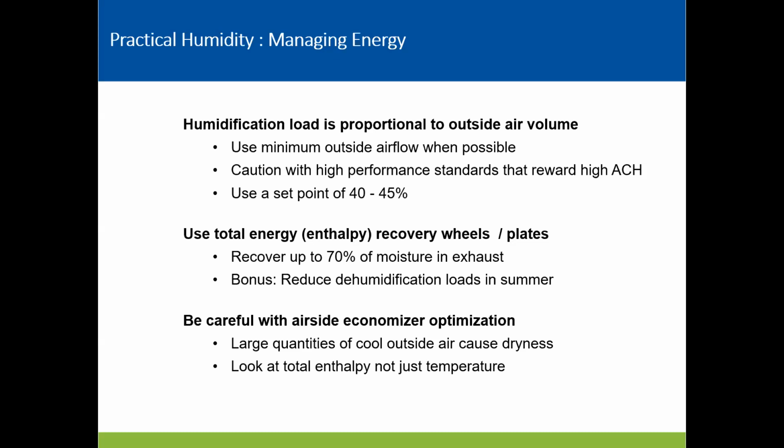And I mentioned economizers. Be careful with the high air changes and bringing in the moisture. Best practice here is to look for total enthalpy and not just focus on the temperature.